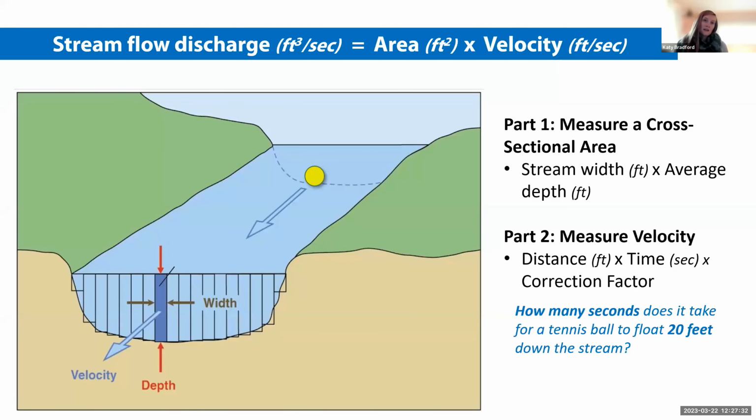We do the float method. So when we're at trainings, I find it valuable to teach the volunteers the equation that we're using so they understand the different components that add up to getting that stream flow discharge reading that they're going to get, because this is definitely the most tricky parameter that we teach, and it does confuse people. So it takes a little extra time. It takes like an hour to teach it. So our units are in cubic feet per second.